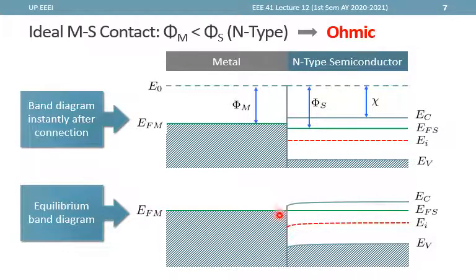And then basically connect the two end lines. Now, how do we get a clue on how the energy band diagram will bend upwards or downwards? We can imagine that the Fermi level at the metal stays the same relative to the other.